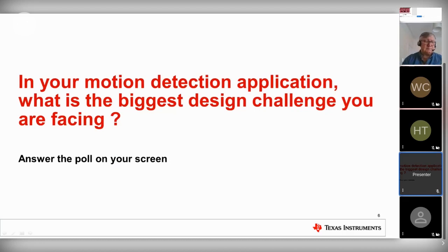It's in fact linked to antenna as well. Here we have one of our modules, the ASK module. It's 55 by 55 millimeters. You see the black in the middle is a single chip solution, and then you have the antenna on top: 4 receive and 3 transmit antennas.